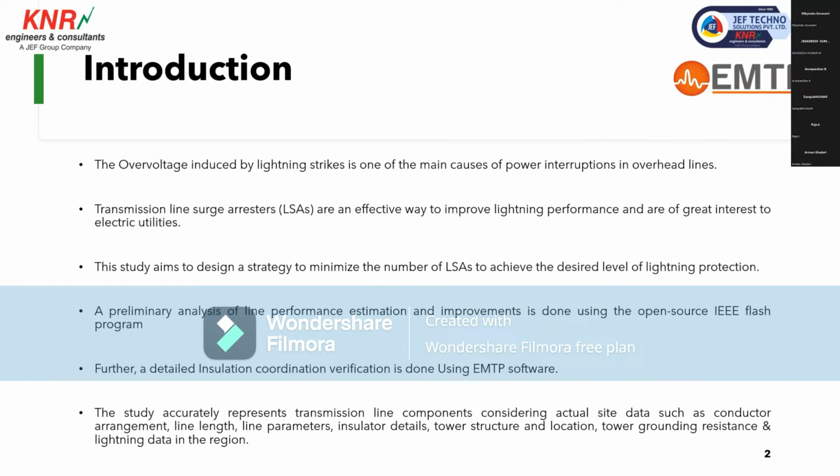any systems. Because when we compare other mitigation techniques such as addition of additional ground wires or increasing the length of the insulator, we have lots of limitations and we need some design changes in the tower, which are all things difficult to implement these mitigations. And in addition to this, the LSA's nonlinear characteristics has a superior advantage and makes an ideal choice as a mitigation technique in many scenarios.